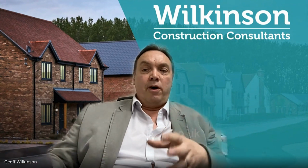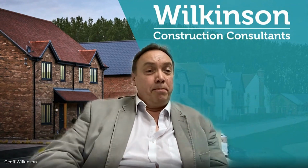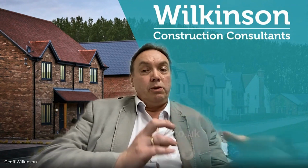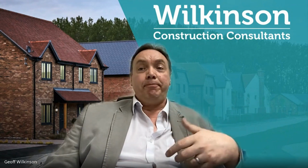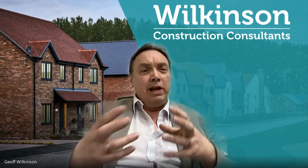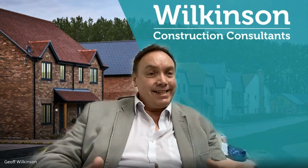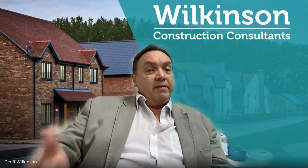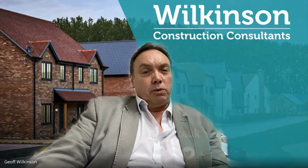Now, that normally involves getting a specialist company in to dig some boreholes or trial holes on the site and do some investigation into what you might actually have on that particular site. They'll be looking for things like chemicals, contaminants, gases, what the soil itself is, whether there's previous fill. So all of those bits of information really need to be incorporated into your design report.